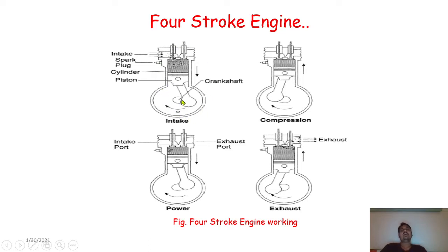Initially, suppose you apply some foot pressure on the kick of the vehicle. At that time, the crankshaft will start to rotate in a clockwise direction, and at the same time, because of the connecting rod, the piston will start to reciprocate, initially from TDC to BDC.